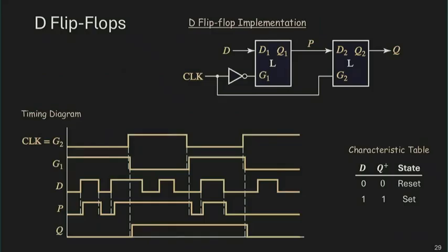What is actually happening? Once you build this flip-flop, what will happen to my output behavior, depending on the clock? So you have one clock, the main clock controlling the second latch. You have the opposite clock, so clock gets negated for the first latch.